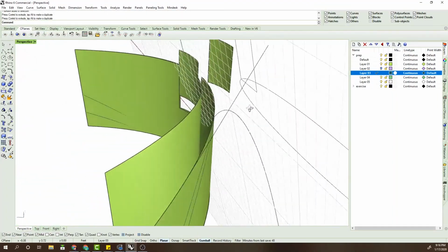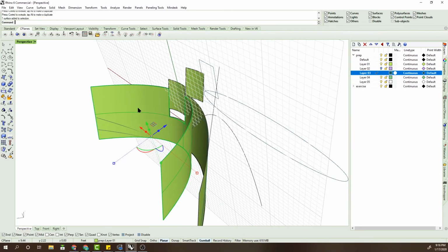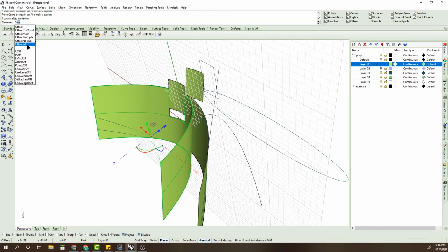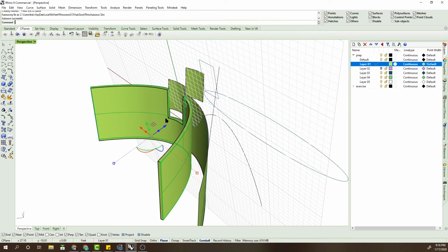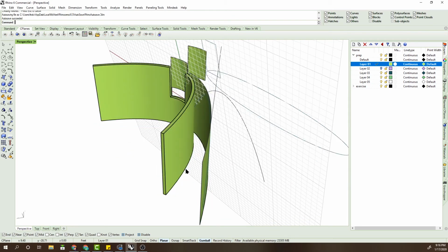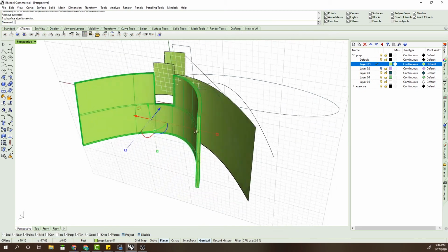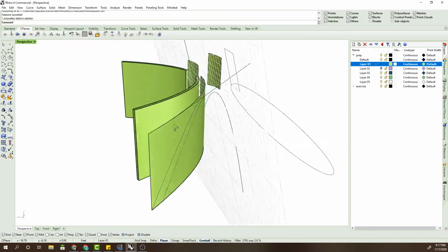And then finally, if you want to make this more solid, go-to command is going to be your extrude surface or offset surface. So offset surface, that's going to point the direction. I could flip it if I wanted to. I'll go this direction. I'll set the distance to be like 6 inches. If this is a wall per se, I'm going to keep it solid. And delete input, no, I'll keep it around. Hitting spacebar accepts that. Now I've got my original surface available and the poly surface. So anyway, that just gives you a sense of what's going on.